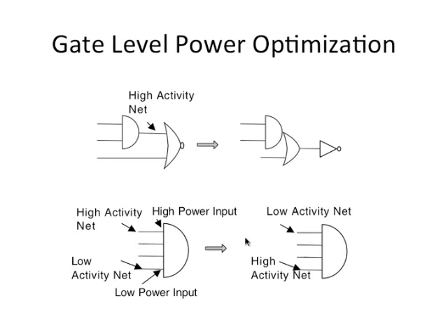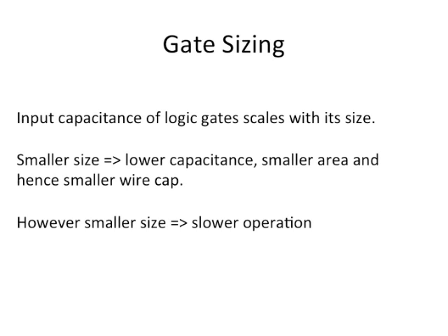You are getting the same functionality, but that net is being connected to an input pin which has lower capacitance. So this is an example of a local transformation in the circuit structure which preserves the functionality but gives you lower power. This is probably an example where speed doesn't get impacted, but you're still getting some benefit in power reduction. But these give you small amounts of power reduction, not large numbers.